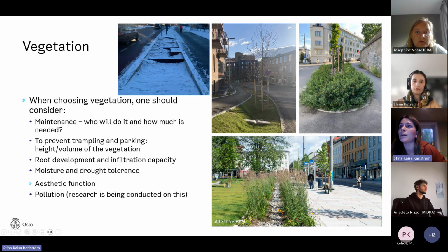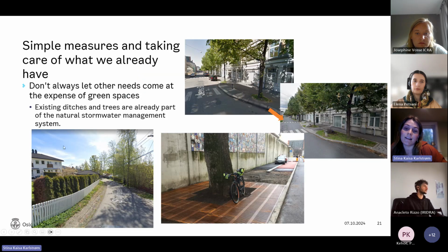So the last thing that I think is important is to maximize the green spaces and utilize leftover areas. We must try to preserve green spaces wherever possible, and they naturally contribute to stormwater management as they are. Additionally, leftover urban spaces can often be repurposed for stormwater infrastructure. And the reason this point is so important to me is that I've seen a lot of horrific things done where I think you could have had a very different outcome had you considered the green infrastructure from the beginning.